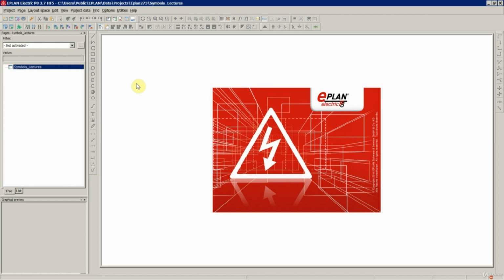So when you have these default symbol libraries that come together with the EPLAN installation like IEC or NFP or GB or any other, so everyone in the world, when they install EPLAN, they have already these symbol libraries. But when you create your custom symbol library, and you forget to include that one in your project where you need those symbols, then you have a problem.